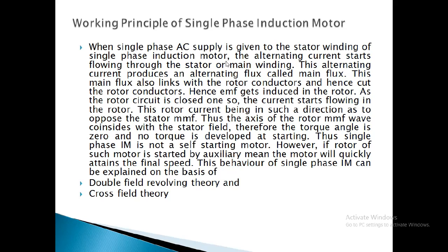This alternating current produces an alternating flux called the main flux, and this main flux links with the rotor conductors and cuts them. Hence EMF is induced in the rotor. This is due to Faraday's law of electromagnetic induction.